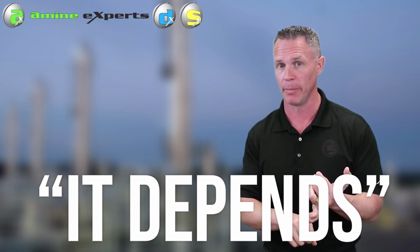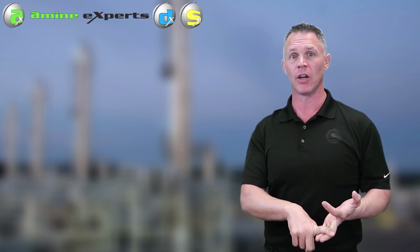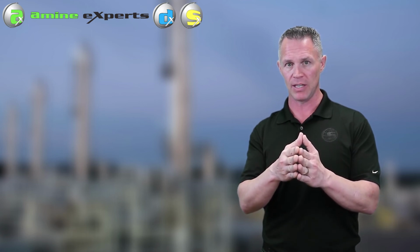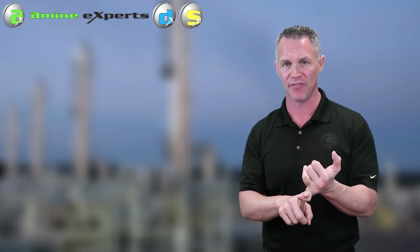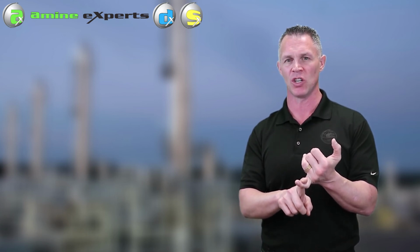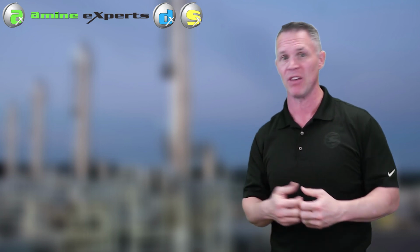It depends on the hydrocarbon composition of your gas, and on what's more important to you, treated gas H2S spec or liquid carryover. I hope we've given you a number of things to consider when it comes to setting your amine temperature. You definitely don't want it any warmer than it has to be, because your H2S removal will suffer. And furthermore, the surface tension of the amine is changed when it's warmer. It foams easier, so you can actually make your amine foam easier by heating it up unnecessarily. Lots of food for thought in this topic.